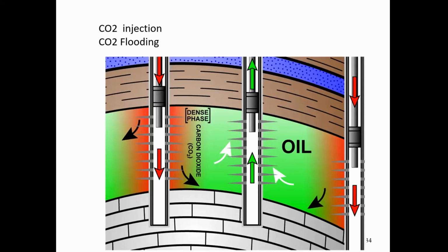0.34 feet per day. The speed of CO2 moving in the rocks in a typical reservoir is equal to 0.34 feet per day. In other words, every 3 days, CO2 will move only 1 foot. And that's a very good way of sweeping, because I don't want to have mobility ratio higher than 1.